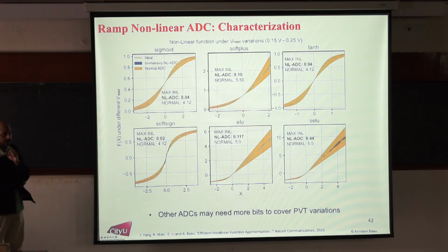Yeah, it's very much possible. If you have a 1-bit ADC and then you reset the bit line again and allow it to integrate again, that whole thing becomes effectively like a sigma delta. So you can also do that. Yeah, possibly. You can also do something like a CCO, current controlled oscillator based ADC. So instead of resetting the bit line, you can have something else.